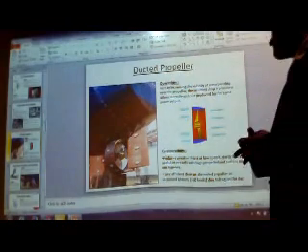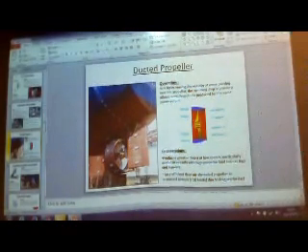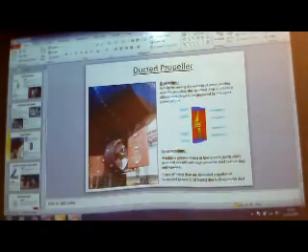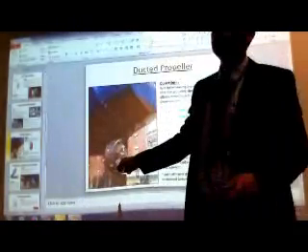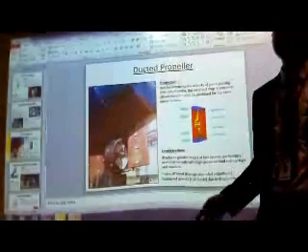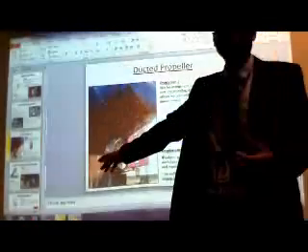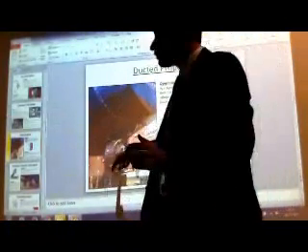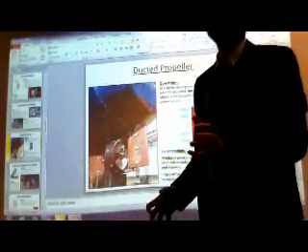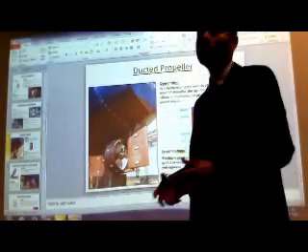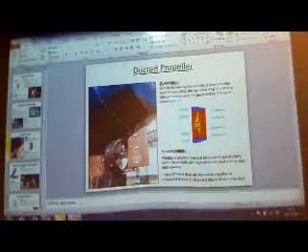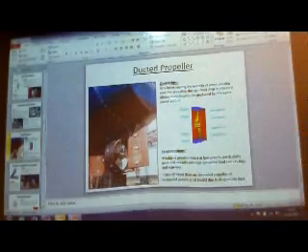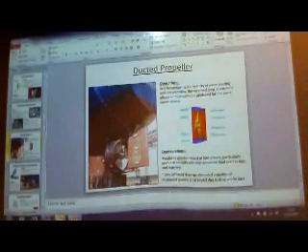It's going to have lesser efficiency than unshrouded propellers at speeds above 10 knots due to drag on the duct. This additional thing at higher speed is going to be counterproductive because it is going to start creating drag, friction. When a flow is coming around from the ship's side towards this propeller, what is this duct going to cause? Friction, drag. It itself starts converting into drag. Does that make sense? Then at higher speeds, it will start affecting the efficiency.